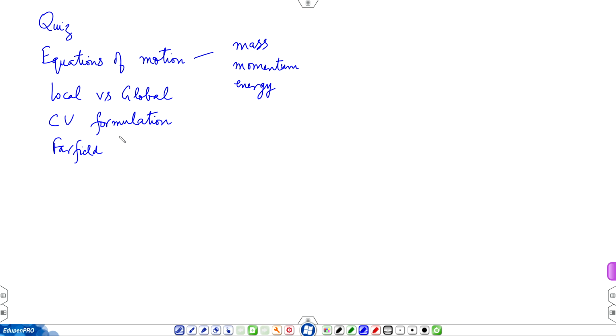But in general, in almost all fluid mechanics problems, when you see a problem, you ask, is it internal flow or external flow? Okay. So, there is no far field in internal flow. If you recall the flow through a tube problem, pressure was decreasing all the time along the length of the tube. There was no recovery of pressure, which happens in an external flow situation. Okay. So, if you introduce an object in a flow field, locally the field is disturbed and then it recovers. So, that is external flow, where far field comes into picture.